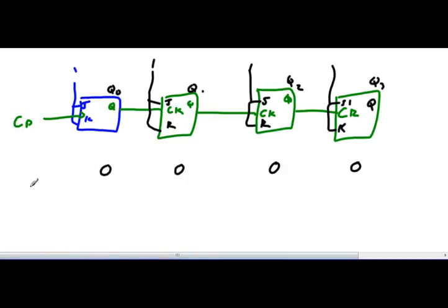Okay? And the clock pulse happens. Boom. What happens? Well, this one toggles. Wait a minute, that one toggled. Boom. This one toggles. Boom. That one toggles. Boom. We just went from 0, 0, 0, 0 to 1, 1, 1, 1. All right, it's going to happen again. The clock pulse happens again. He toggles to a 0. Nothing happens. Nothing happens. Nothing happens.